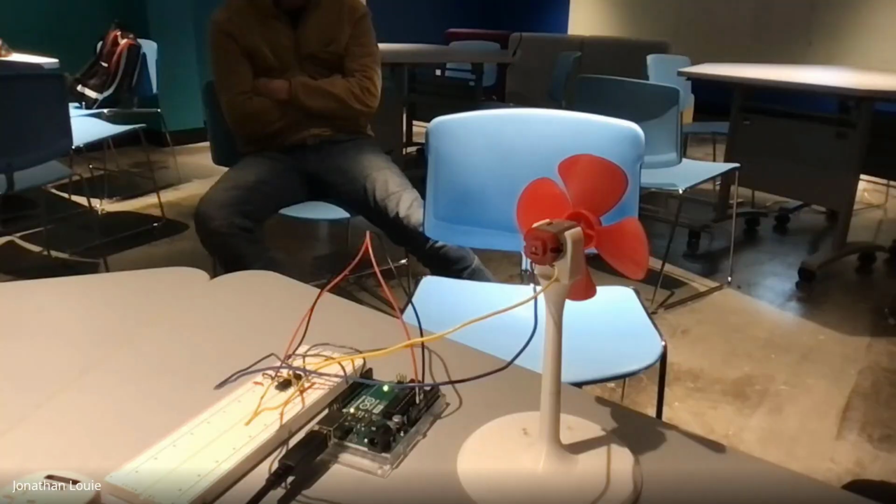Yeah, that reminds me, another common application of embedded systems we often don't think about is a hotel room RFID card. Often if you were to peel it apart, you'd see there's an antenna around the edge. And I guess a credit card can be a similar example. Yep. And the credit card reader or the hotel door reader actually emits radio waves that power the antenna, which then generates just enough power to power that tiny little processor that's in the hotel room card. And there's some memory on there and some encryption algorithms to ensure that the keys that the door expects are the keys that are actually present in the card.